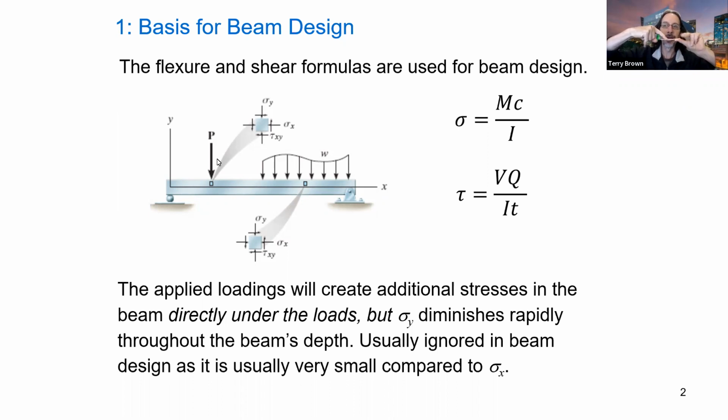Now you could model that as a point load like we've done in the PowerPoint here, or you can model it as a small distributed load over a small area. Now, whether you do it one way or the other, what will happen is you'll get stresses developed underneath that loading point, okay, which are not calculated by these two formulae. Right? But usually we can ignore those.